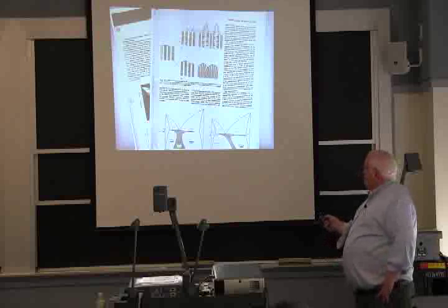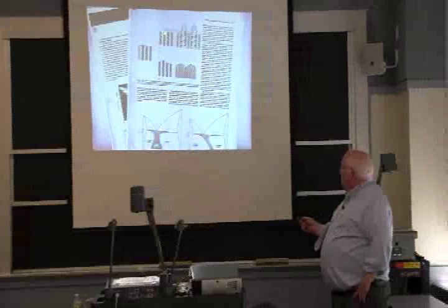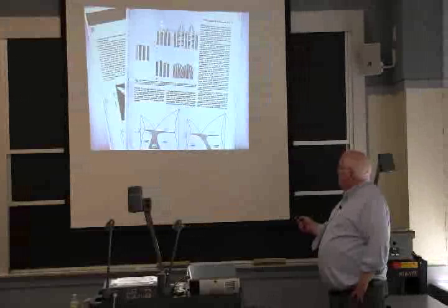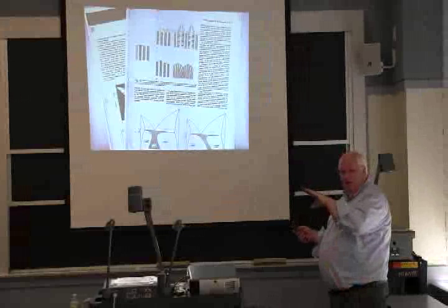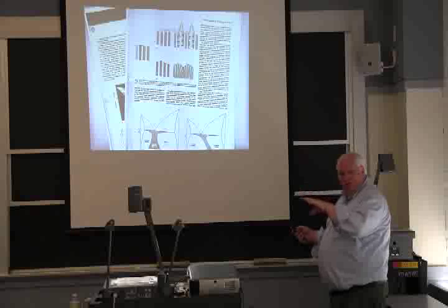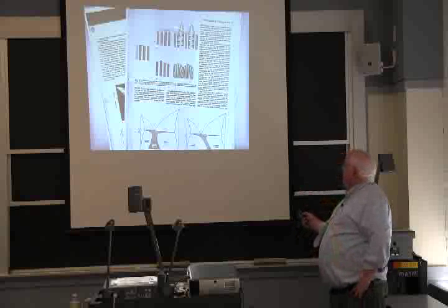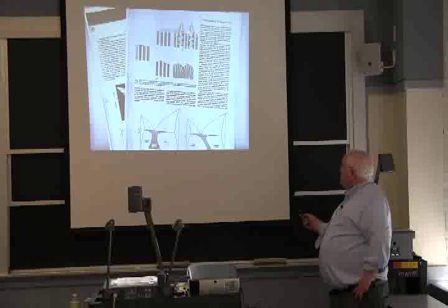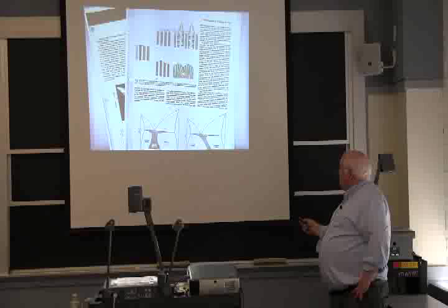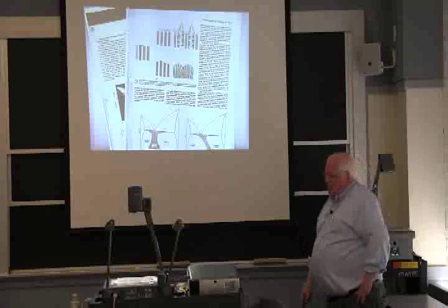If I get John's thesis out again, I'll show you where the ferrite has a higher melting point than the austenite, and it actually gets fingers of ferrite sticking out into the melt as you're solidifying. This is where you actually get a breakdown in instability called dendrites, and you can see the little branches on the trees. This is cellular solidification. This is a type of cellular solidification that we sometimes call the eutectic. It's a very fine cellular structure.